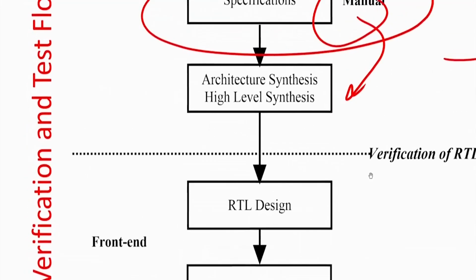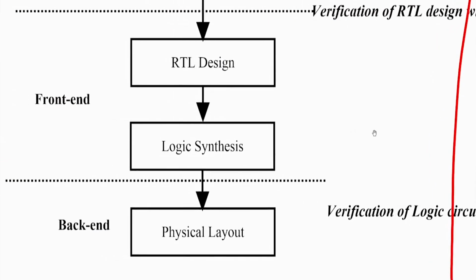This is a full-fledged CAD flow, because of course we know that a Karnaugh map can generally solve up to 5 variables, Quine-McCluskey can extend it to some more variables, but in case of circuits there will be more than 1000 variables, or even much larger than that. Then there are optimized tools, the algorithm is called Espresso, which is a heuristic that solves this in a much faster manner.